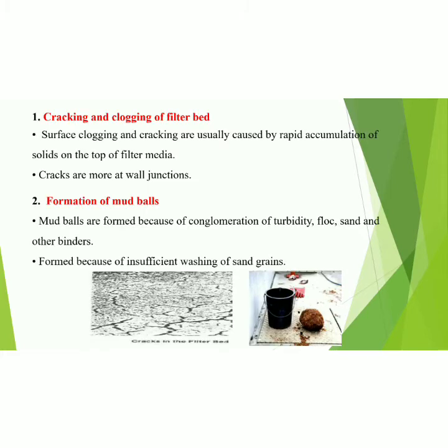What happens actually during the rapid sand filters? Cracking and clogging of filter bed, that is, surface clogging and cracking, are usually caused by rapid accumulation of solids on the top of the filter media. Cracks are more at wall junctions.